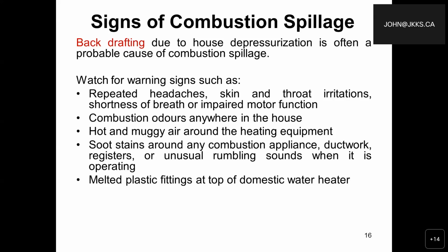So again, this depressurization can be caused by a powerful exhaust fan or even weak chimney vents and wind downdrafts. Again, the hot gases have to rise through the flue and exit the home because they're not as dense as indoor air. The pressure differential that allows for the release of these combustion gases can be overcome by usually low indoor air pressure caused by high rate of expulsion into the outdoors through exhaust fans, fireplaces, and dryers.